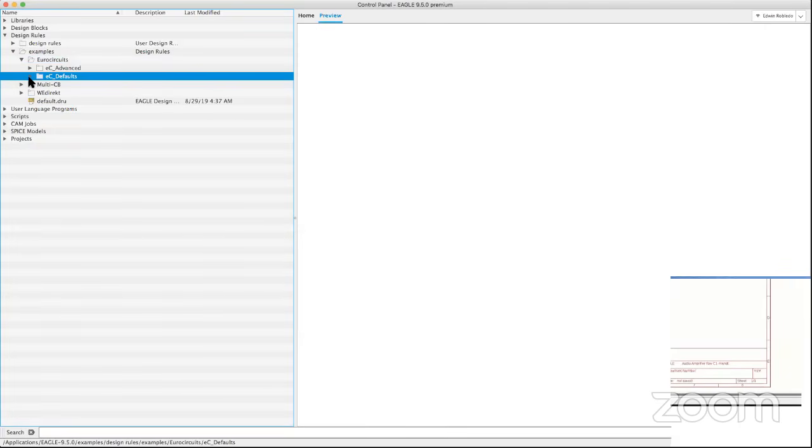These are just the rules which you should follow on your circuit board. That way it's manufacturable or prototype without any errors. It gives you clearances, it gives you distances, sizes for vias, holes, and so forth. It's just the rules that your board is going to be checked against, okay?